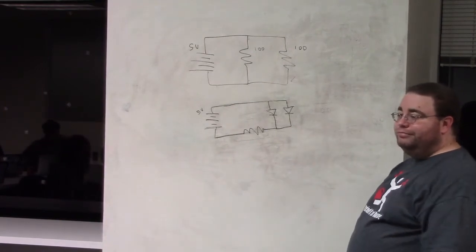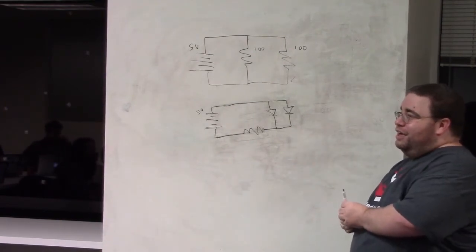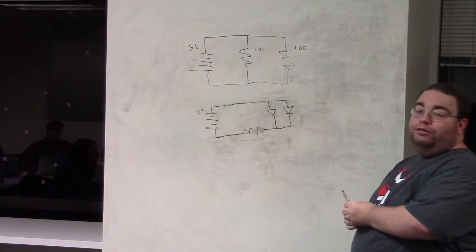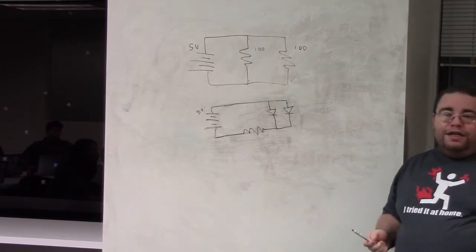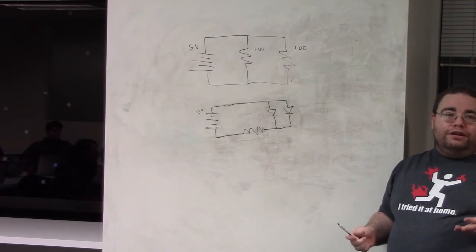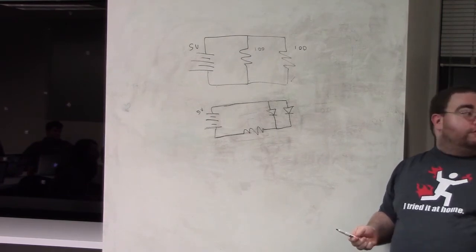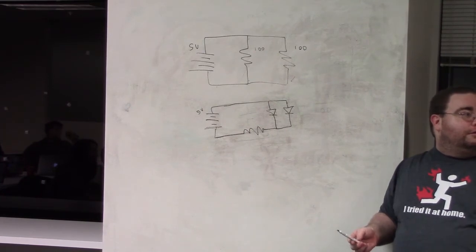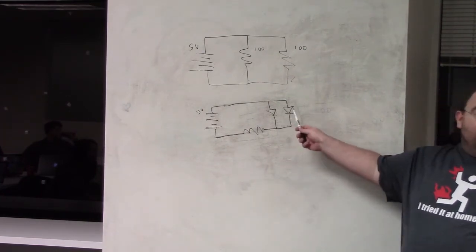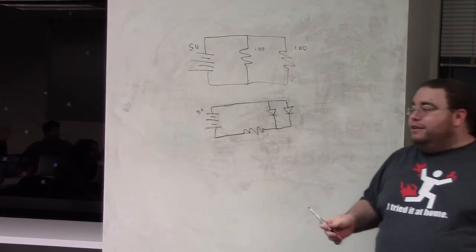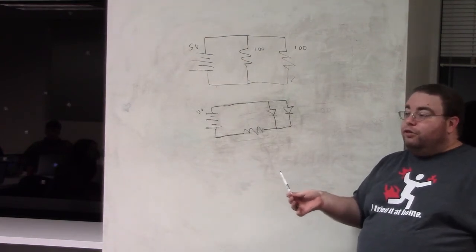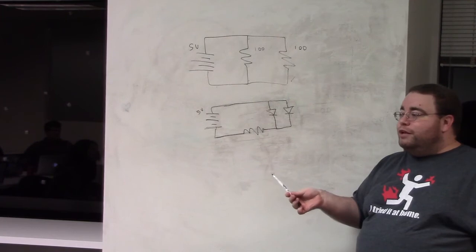Is that why Christmas lights are crap? Because the electron's going to take the path. Right. Electrons will take the path that is least resistance in proportion to the total resistance. Because remember, if they always took the path of least resistance, then the voltage divider wouldn't work. Some of them have got to go back down that 300 ohm resistor. But here it's almost like a short. Yeah, because these things are not ohmic devices. Basically, diodes and LEDs and semiconductors in general don't play nicely with Ohm's law. They don't behave the way that Ohm would make you think they do.